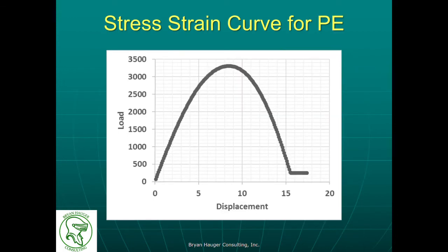So at the first mention of the stress-strain curve for polyethylene, this is the image that jumps into the minds of many people. In this simulated or idealized stress-strain curve for polyethylene, you'll see several features that are familiar. At the start, we have a rapid increase of stress and strain that gives rise to the Young's modulus or elastic modulus. The load increases with increasing strain until we near the yield point of the material, where there is a plateau and we achieve yield.